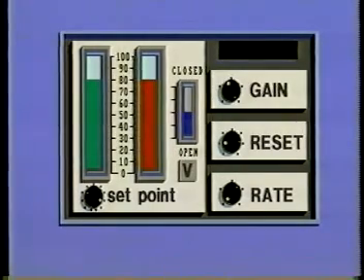When a load change occurs, the temperature drops rapidly. The derivative unit immediately acts along with the proportional unit to produce additional valve movement temporarily. As the temperature levels off, the derivative action decreases. Once the temperature stops changing, the valve returns to the position dictated by proportional and integral action.